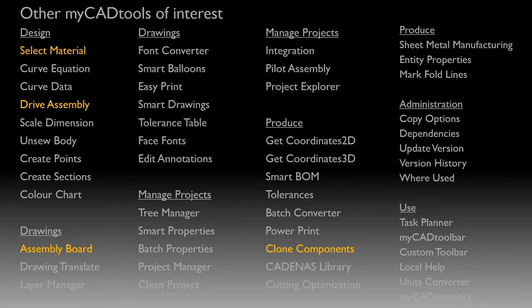And based upon that range, we can then pick out the envelopes for movement and also calculate trajectory points from that information. Select Material allows us to filter down the material databases while working in SOLIDWORKS. We can find a material that fits our needs for a specific job. Once we've found the right material, we can then customize hatching and scale, and we can also input custom properties all really quickly within the document.